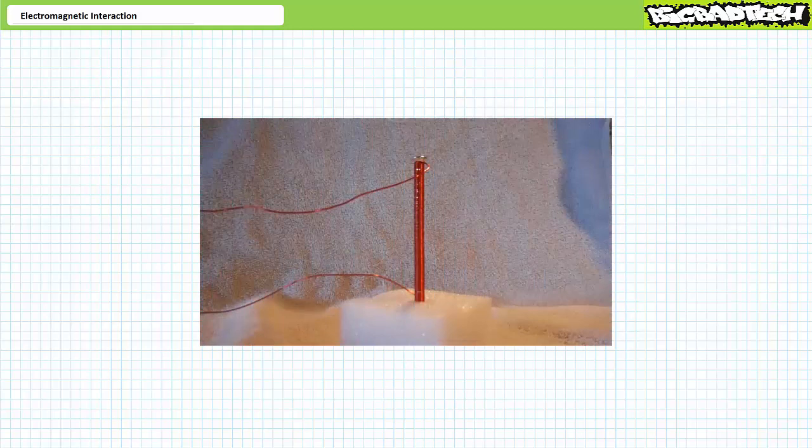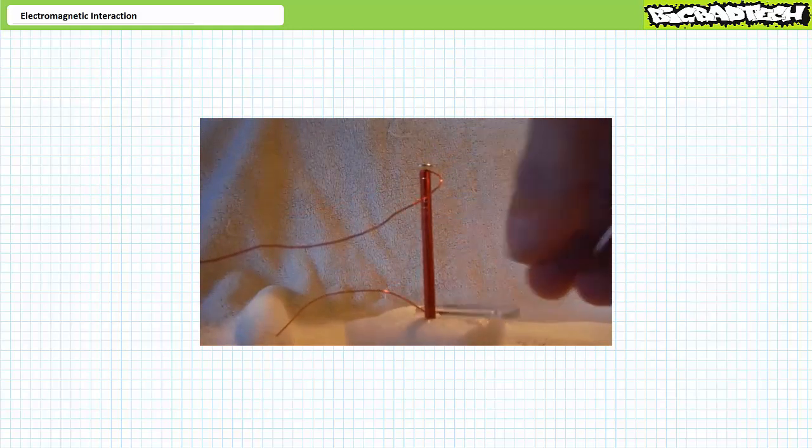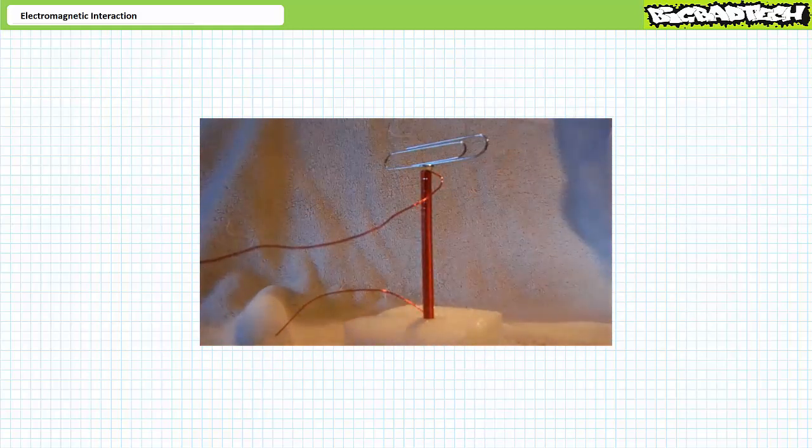Consider a coil of wire covered with a thin resin insulator wrapped around an iron nail. That iron nail is electrically isolated from the wire. However, the permeability of the iron concentrates the lines of magnetic force better than would free space. With no current traveling through the wire, no magnetism is observed. The moment current starts flowing in the coil, magnetism is observed. When current flow stops, the magnet stops.